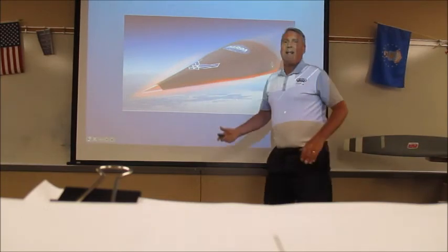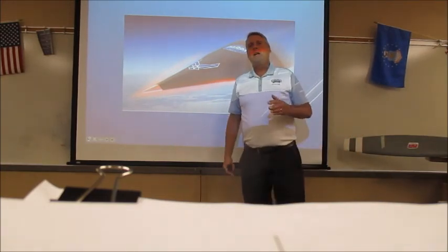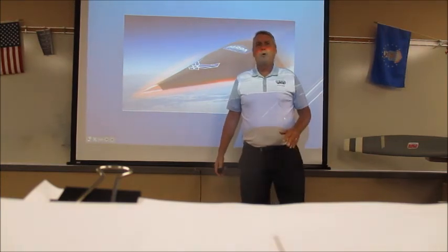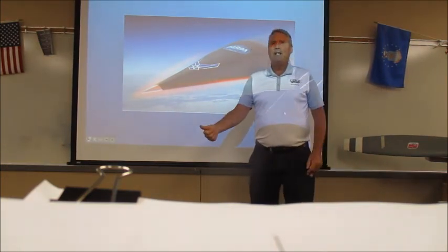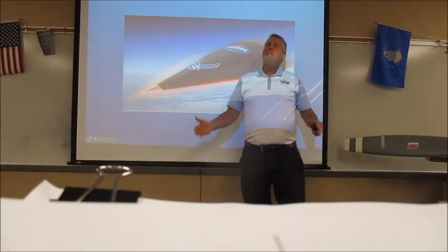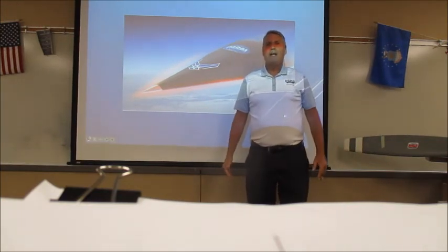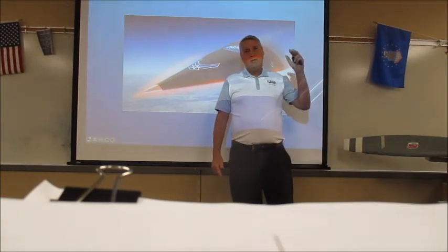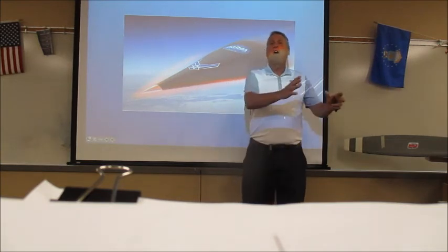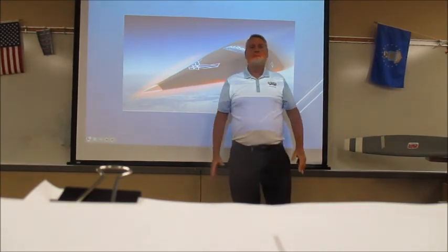So, that's it. That was just a little down and dirty preview of primary and secondary flight controls. Primary flight controls, you absolutely need them. They're going to have redundancy built in. You might have an A system hydraulics, B system hydraulics, C system hydraulics, and they're all feeding these flight controls separately.